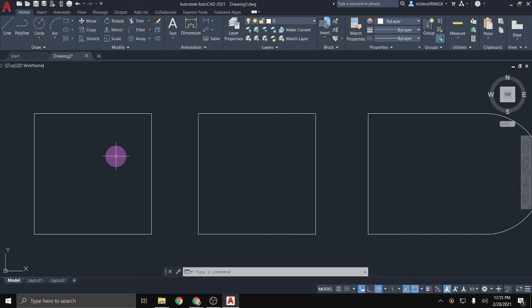So the benefit of polyline versus the line tool with architecture really comes from our wall thicknesses. Within our hand drawings, we had to show how thick all of our walls were. And in AutoCAD, we break that down even more because not only are we showing our overall wall thickness, but we're showing the thickness of every layer of that wall.